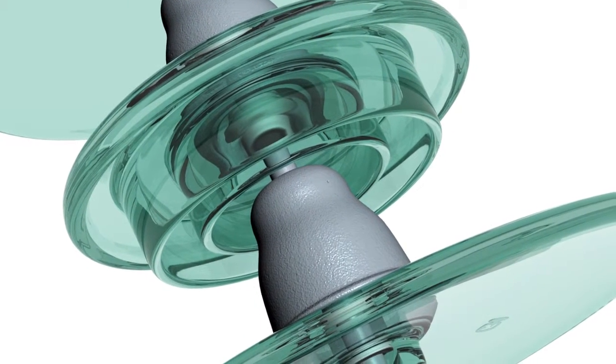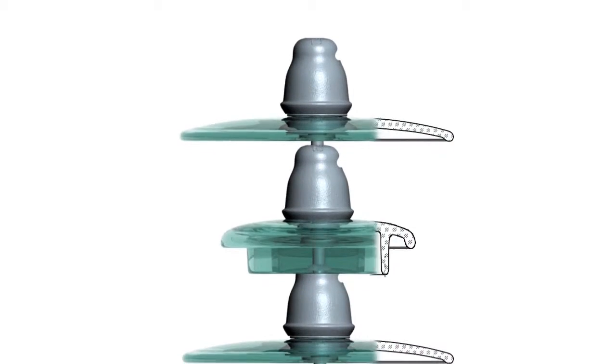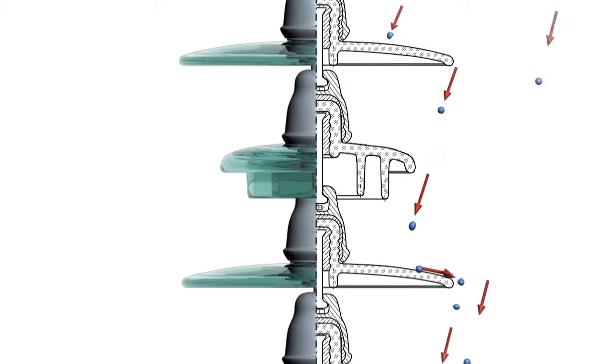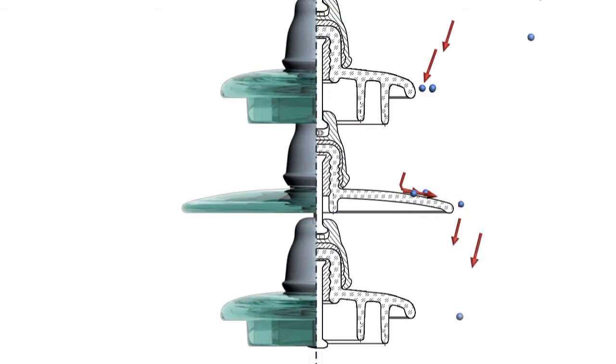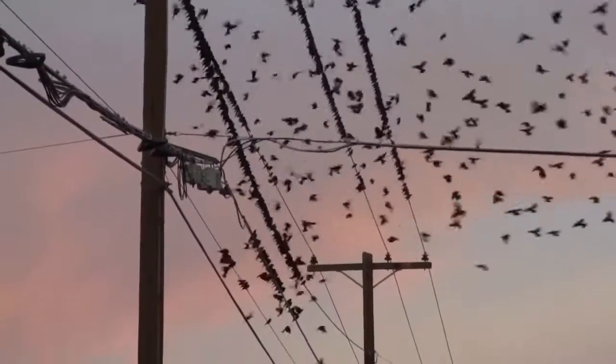Besides the effective protection from mixed contaminations, the mixed type string unit is stable to flashover in the air, snow accretion, and icing. Apart from fighting against natural and industrial deposits, it is also important to provide protection in conditions of huge amounts of biological contaminations from birds.